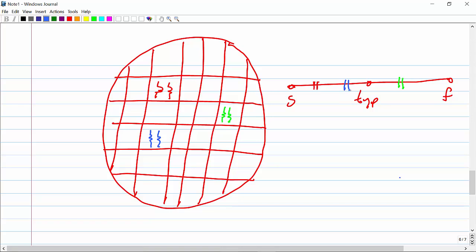What I want to say is you have to identify the difference between the process corner and the mismatch. Process corner means the difference between this and this. The difference between these two is called process corner difference, and the difference between these two resistors is called the mismatch. The difference between these two is called process variation.